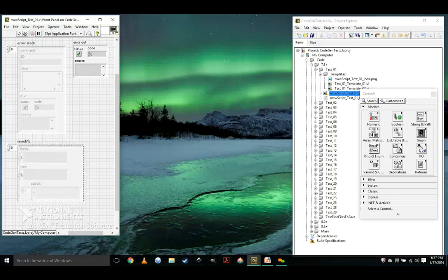And there are also ways to handle, let's say you have some sub-VIs that you use in your scripting, but they're not in any of your APIs. And you don't want people to save these and then have links to your sub-VIs wherever they are. So I think there's a tag called Save Me, and it can be almost anything. It just has to be on the root of the block diagram and have the name Save Me. And if that's in a sub-VI, when the Codegen engine runs through it, it'll save that with the other code and relink it so that it won't mess up your scripting code. I can't remember the details of that, but it's in the PDF.